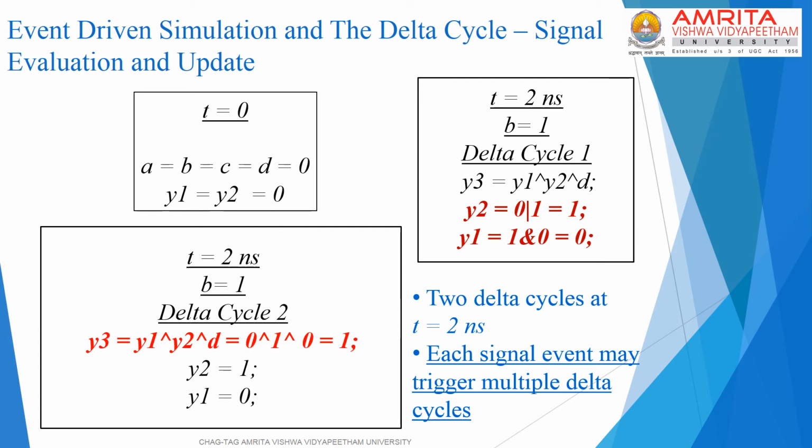The values of signals that are computed at different simulation times are dumped into a file which is called the value change dump. So this dump will be used by a waveform viewer to create a display of the signal levels at different simulation times.